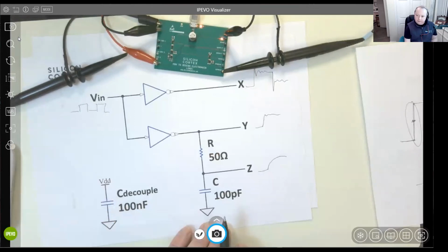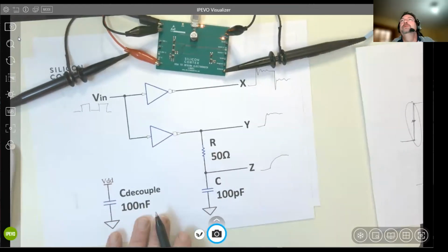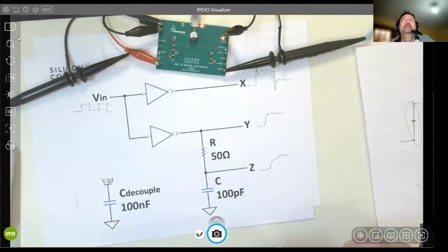Yeah, I mean you fixed it with an inverter, a Schmitt Trigger rather. I wish we could have fixed it with a Schmitt Trigger. I ended up fixing it in software because we weren't able to do anything with the hardware. Basically, I fixed it by making the strobe pulse so short that it really didn't get enough energy to overshoot. Right. But it was the only tool left in the box at that point.